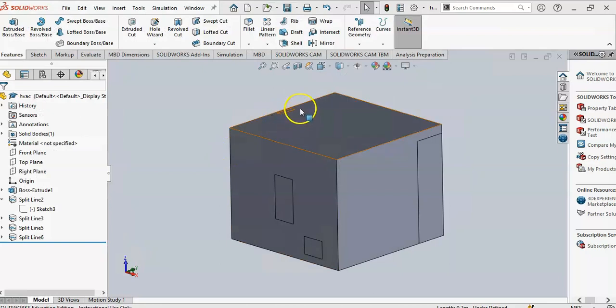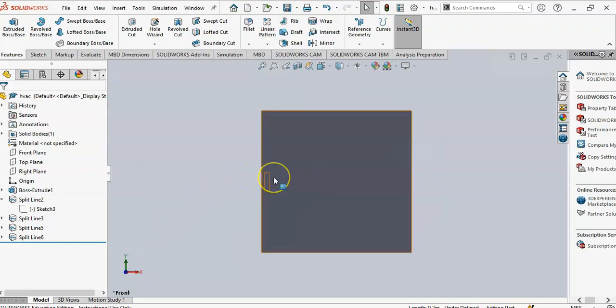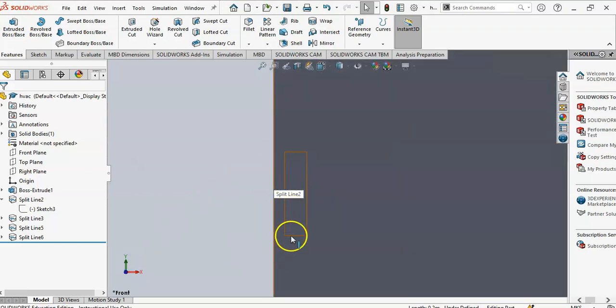One last adjustment I want to make to this, and that's to increase the size of the inlet here. That's so we can reduce the flow velocity in for the same flow rate, which will make the calculation more stable, which we'll see a bit more about in the simulation part of this exercise. So I take the view from above by clicking on the Z-axis here and zoom in on that. I'm going to increase this from 0.1 meters to 0.2, increase this from 0.4 meters to 0.8, giving an overall increase in the area of a factor of 4.